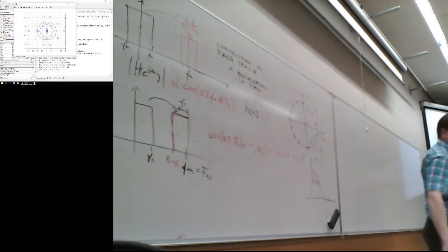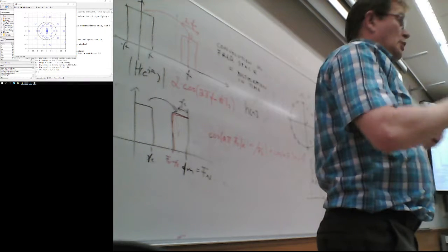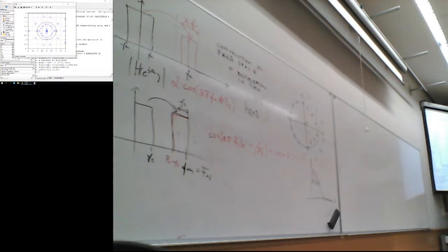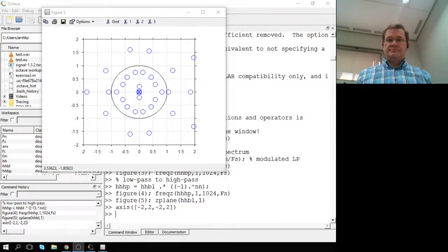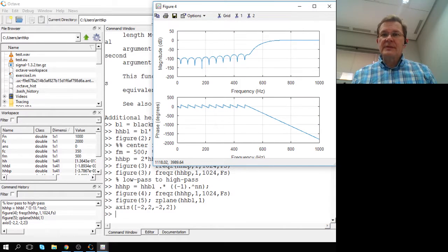But there are also some computing accuracy issues on this one. This is already a 40th order filter. So MATLAB tries to solve the 40th order polynomial. 20 would be okay. 80 is a piece of cake, but 40 requires a little bit more computing accuracy, I think. So one singular or nearly singular value actually messes up everything. Okay, but anyway, I'm more or less happy when I just see this kind of picture.